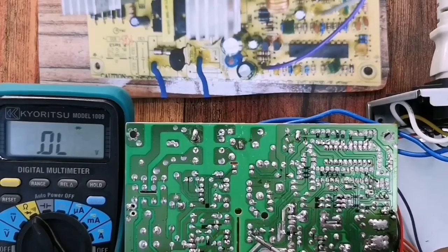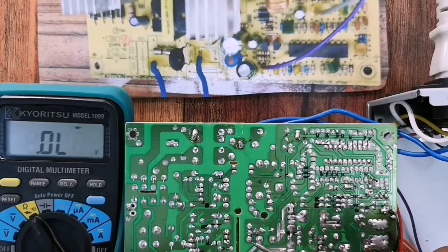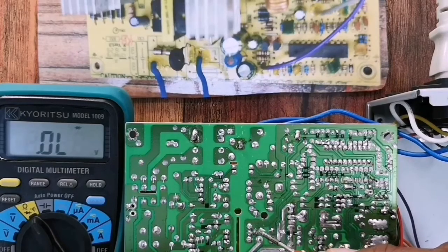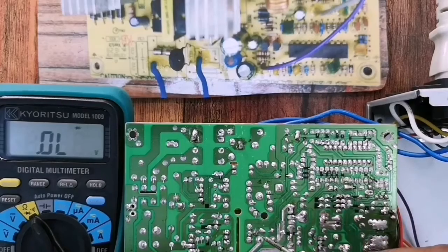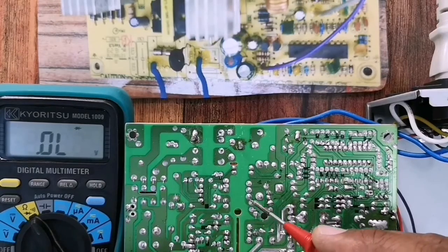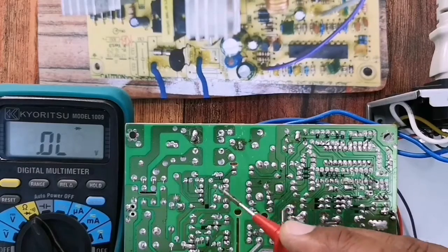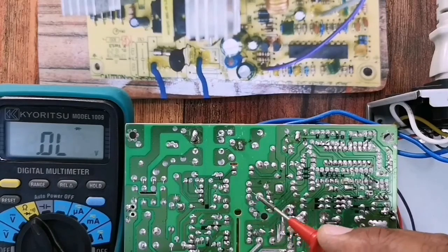The middle pin of the transformer, I believe, is the one providing the supply voltage to both sides of windings, which are connected to the transistors for switching. I think we are getting closer. The pin is getting the supply from one of the windings of the 5 volt standby transformer.